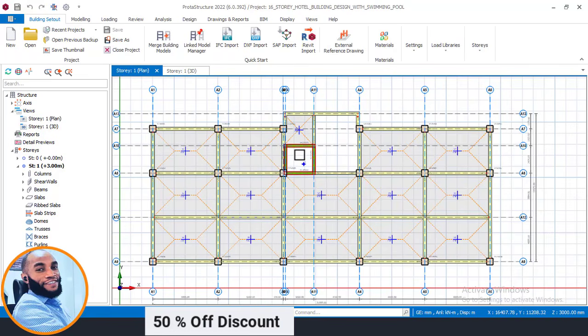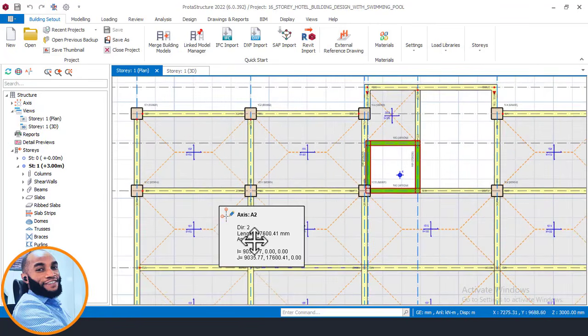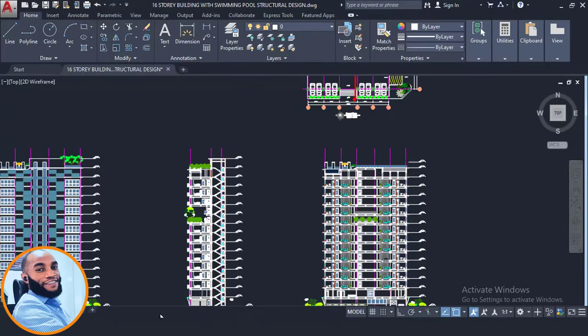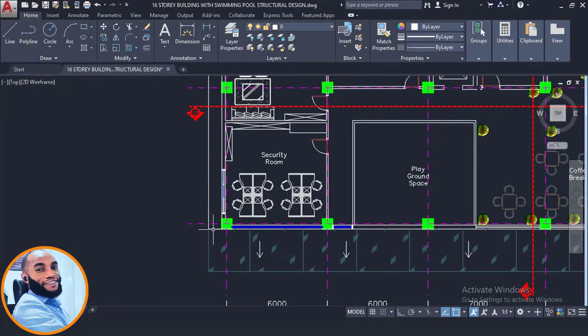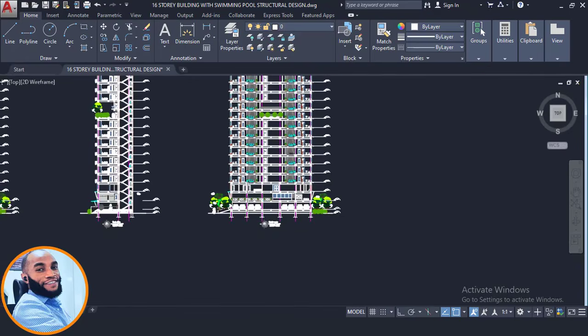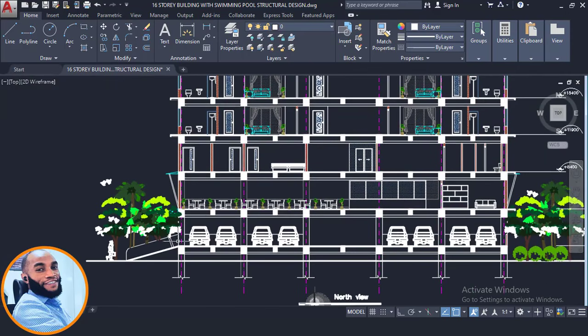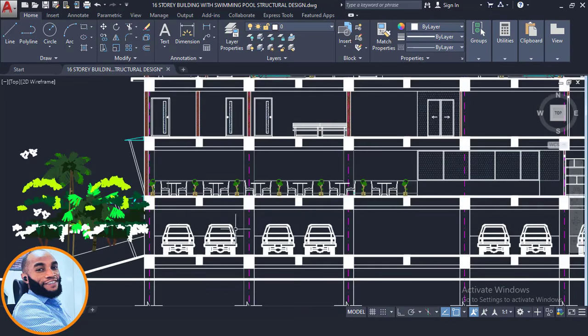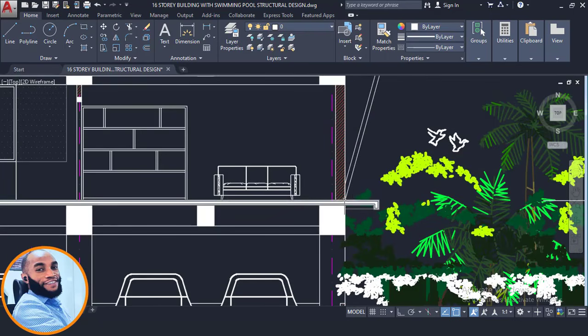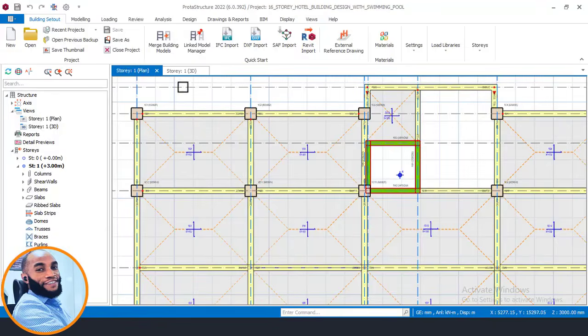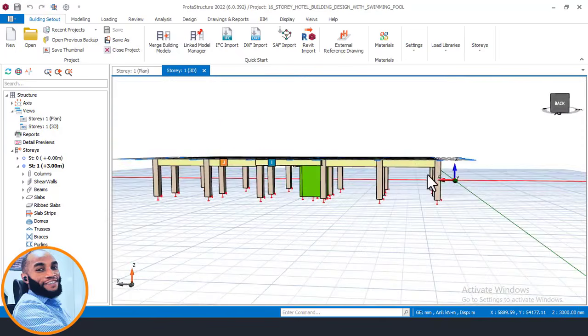So from this place now, the first thing to do once you come here is to create the cantilever slab. If you go and look at the CAD file here, from this story, you can see that there is a cantilever slab along this place. And from our view here, this is the ground floor, and the cantilever slab is found directly on the first slab. We are meant to create our cantilever slab directly from this first slab here.